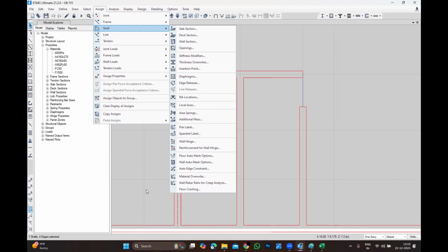So what happened is, whatever he wanted, he did it, because it's internal and nobody is going to notice. Unless the DM inspector observes or hears something, he will not come and check. If not, nobody is going to check it. An entire half floor collapsed. He did so many things. When he demolished, you find 25 millimeter rebar at the bottom. Can you imagine 4 rebars of 25 millimeter at the bottom of a wall? Who would put that? It's a deep beam.